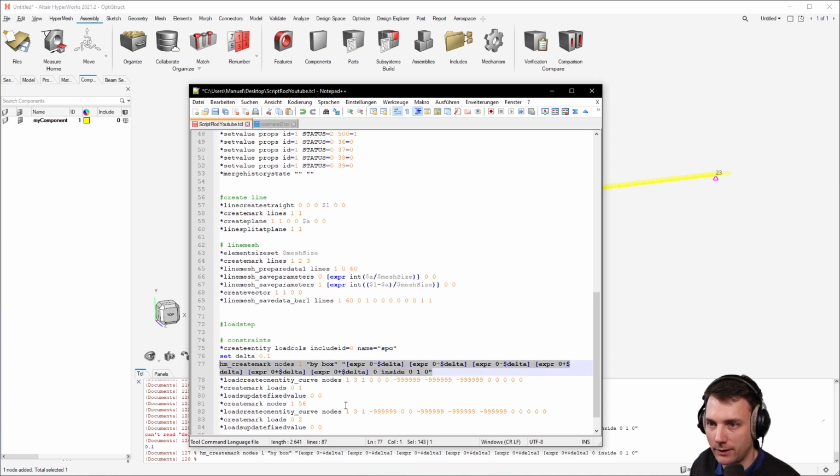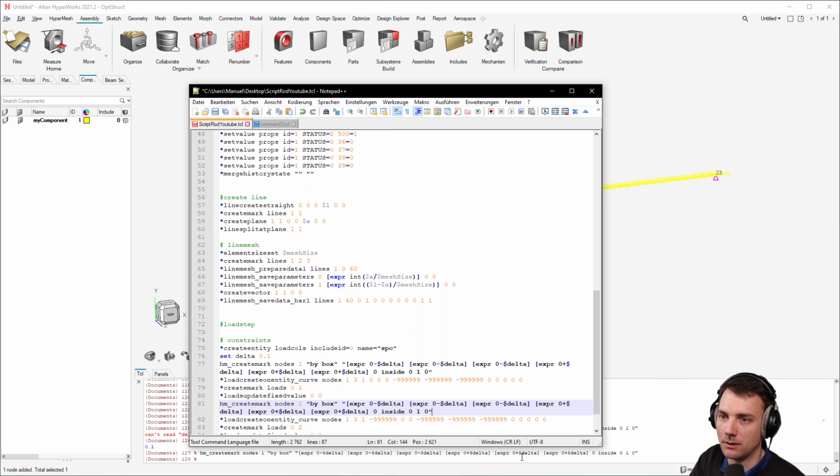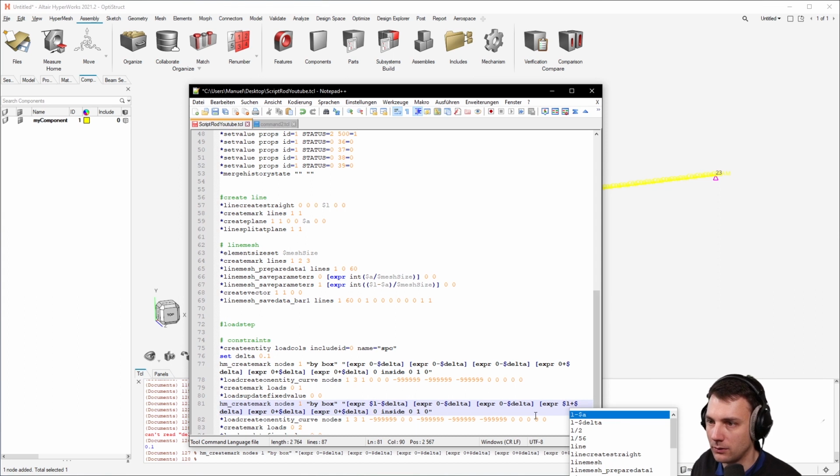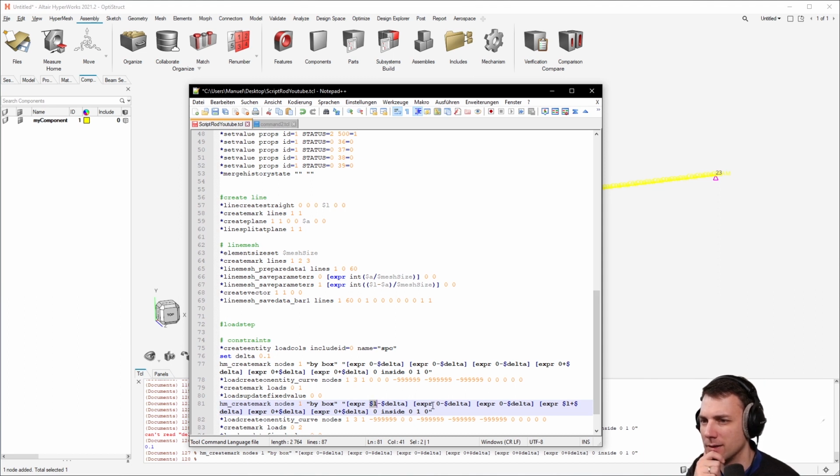And we have to use the same thing here for this. But here, instead of 0, we have to use L for the X coordinate, here and here. Because our bounding box, yeah, only here and here. Because we want to create a bounding box around this node. And this node is located at L, 0, 0. And L minus delta. Now Y would be 0 minus delta and C also 0 minus delta. That seems legit. Let's see.